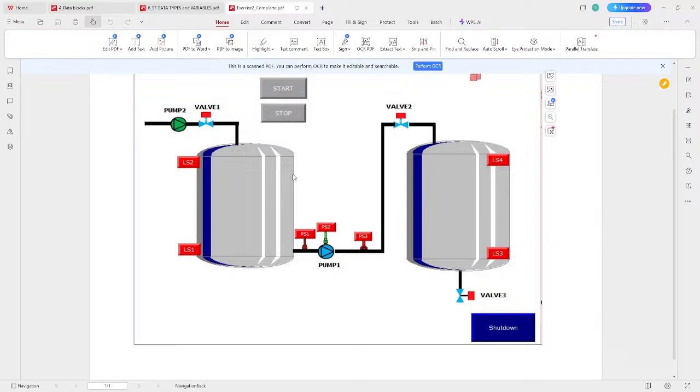It's just a flow switch too. It detects first that there is flow. If you press start and there's no flow, it gives you an alarm, a dry run fault, then stops the system. Then you have to reset and restart the system. I would have to look for the full program.